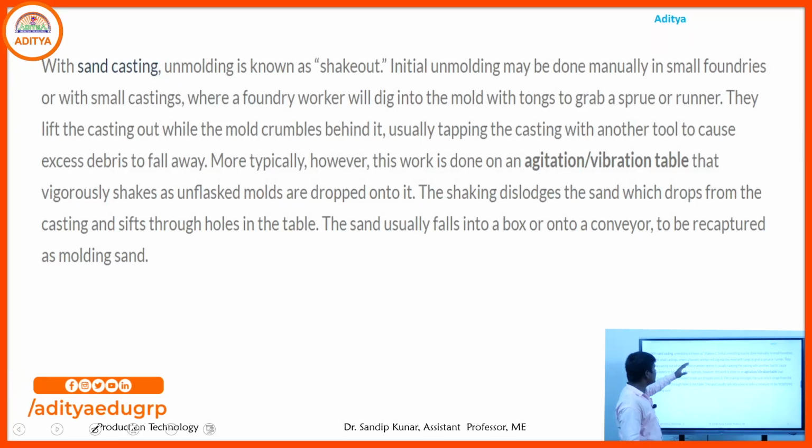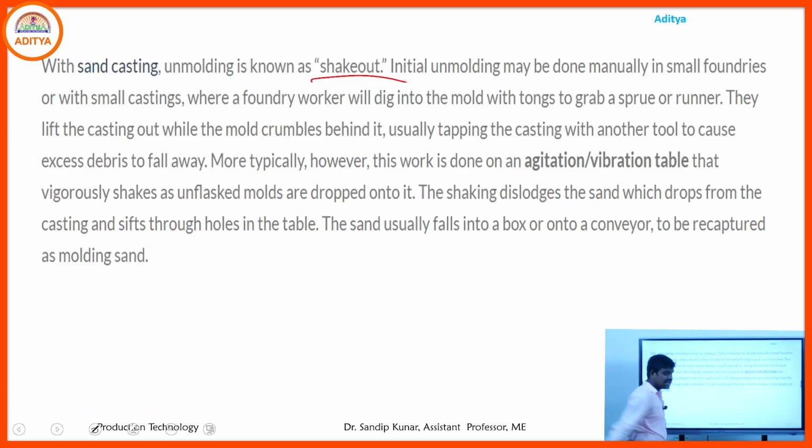Then, unmolding in sand casting is called shake out. Sometimes sand sticks to the particular product, and due to shaking some sand particles are removed from the final product, so some finishing takes place. Okay, and in that case we get the finished product due to shaking.